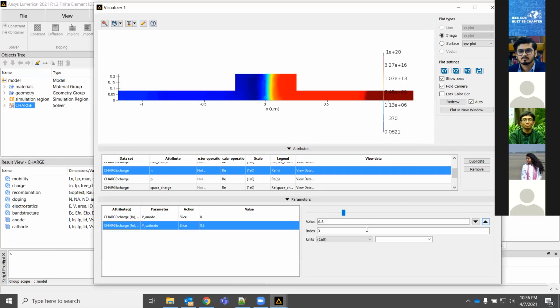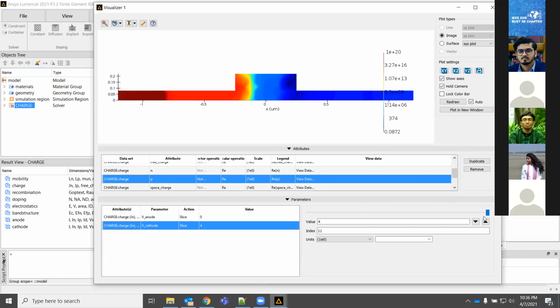And so the charge density in the center of the waveguide is going down. As I go further and further into reverse bias, you can see I'm depleting the charge here and the density is going down. You'll see the same thing for holes. At highest bias, the center is getting depleted of holes. But as I go back to 0, I go back to my initial doping profile, where I had lots of holes in the center as well.